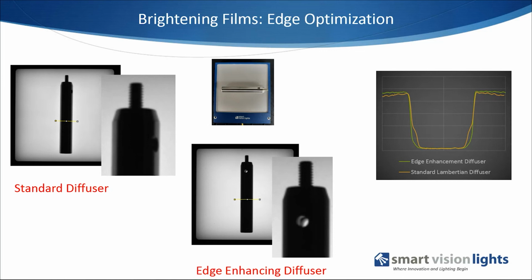You can see that the edges are both fuzzy, you notice the threads are becoming fuzzy, you notice the edge of the cylinder is a little bit fuzzy, and then more than that, you notice that the grayscale is not black on white, but that you get the medium kind of gray along those edges, which make it hard for your machine vision to find that edge.